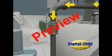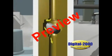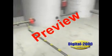But on the day of the accident, the check valve didn't work. The CSB later found that the design of the valve allowed the plug to become misaligned, allowing acetylene to flow back into the water pipe. The gas flowed back through the check valve, through the recycled water line, and out of the open drain valve into the shed. The concentration of acetylene built up to a dangerous level.